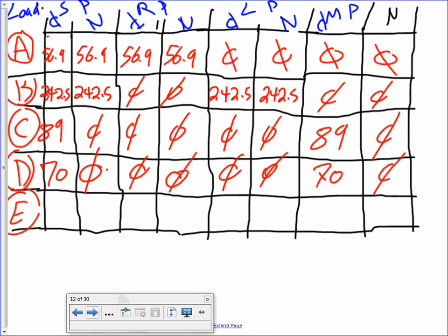Okay. The last step is a little bit confusing for you. Does it make sense, guys, how I allocate chunks of loads into different panels? Now, here's my question for you, Brian. If I don't have a mechanical panel, where would the mechanical load be fed from? It will be directly fed from the main panel. You just don't have a mechanical panel.